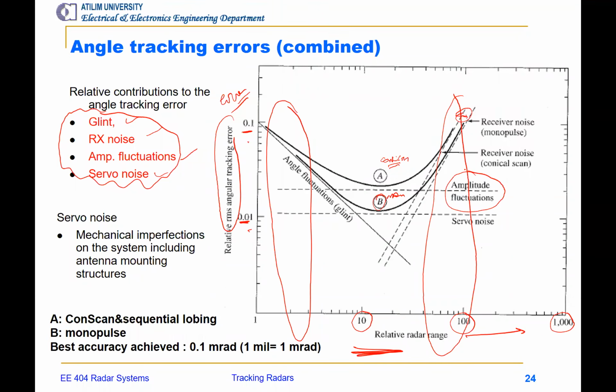So there is going to be amplitude variation when the beams are switched or rotated. But in monopulse, since there is no motion among the beams, all beams are created simultaneously and the received signals are measured simultaneously, so almost no amplitude fluctuation is expected, which is the advantage of monopulse.